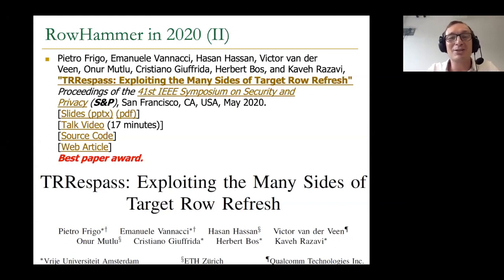Basically, we wanted to actually test this hypothesis, which was not backed by any real theory, if you will, by DRAM manufacturers saying that, okay, these are Rowhammer free, and we tested them, and we basically were able to construct attacks that prove that that hypothesis is false, meaning these chips that are advertised as being protected against Rowhammer completely are not protected.